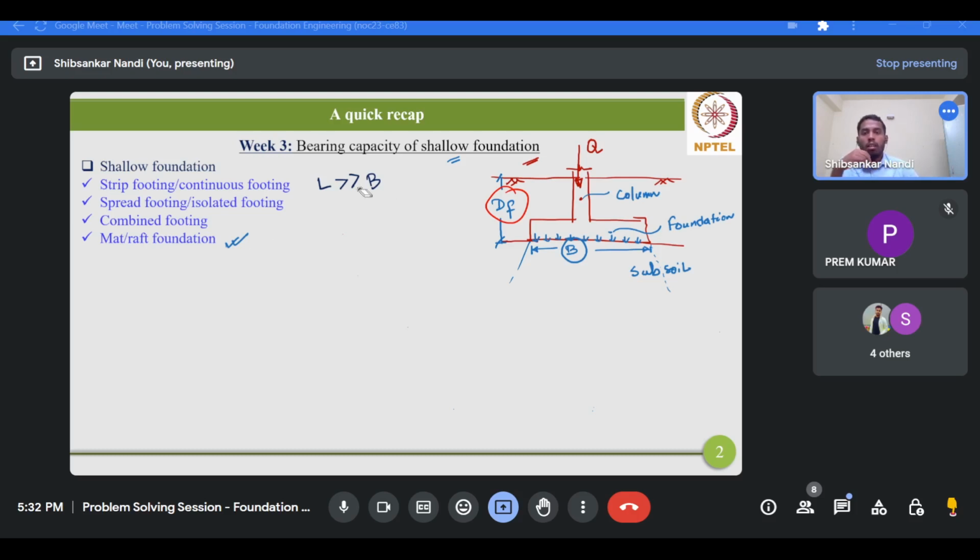Okay. Now coming to the design perspective, just as a little small introduction, we will not discuss in much detail. So this design will be guided by, okay, so again before that, these are the selection criteria for any specific shallow foundation. So this shallow foundation is basically decided by the magnitude of loads, nature of subsoil strata, already discussed, the nature of the superstructure and specific requirements. Okay, you can basically go through the lecture materials which are released on the course portal.